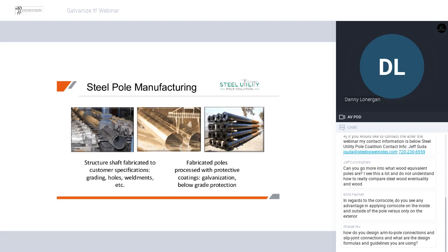So ultimately you have a shaft. If you're mounting an insulator directly to a pole with a 2-bolt connection, you have a connection there that just needs to be studied. The question may ultimately be, is there local buckling or concern of local buckling? The answer is yes. So if you go back to the commentary in 4819, that's exactly what they're saying with respect to connections on tubular structures.